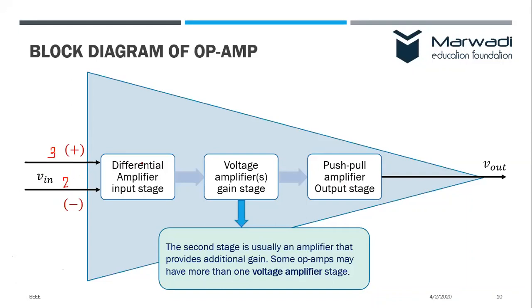Then this amplifier will amplify 3 minus 2, that is 1. So effectively we have 1 volt as the difference, and this 1 volt is considered the input signal, and then it is amplified. That is called a differential amplifier, and it is called voltage difference, right?